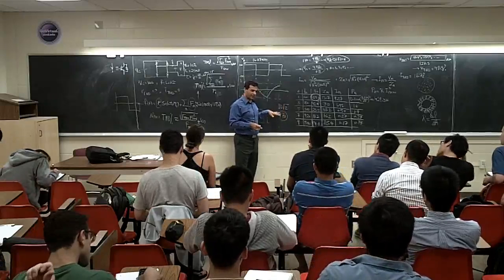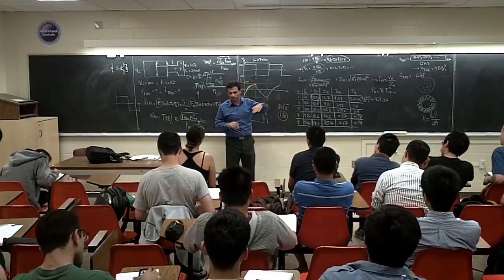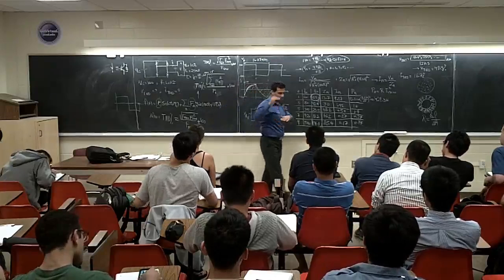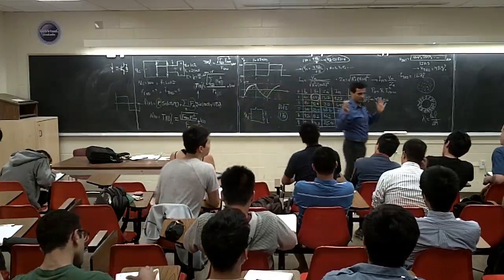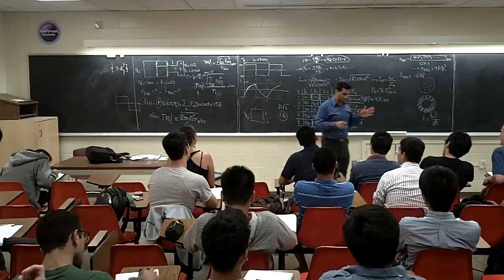You can design it so that when fully charged, everything is good. You get about 120 because your battery is going to start to discharge. So for the full charge, you say, okay, I want to get 120 volt, but when my battery starts to discharge, I don't want to be less than 105 volt.